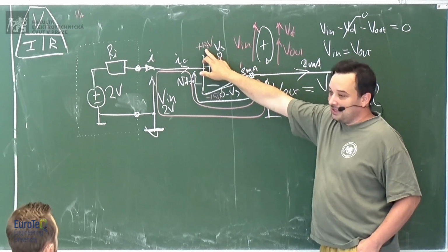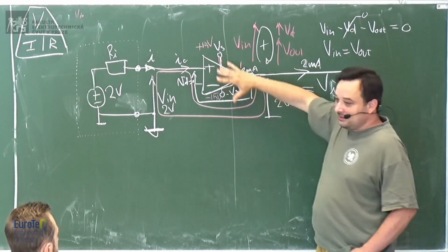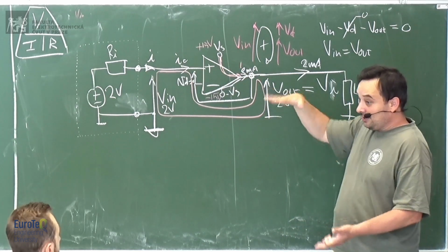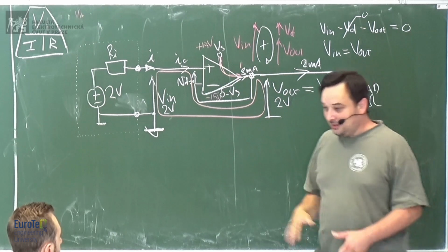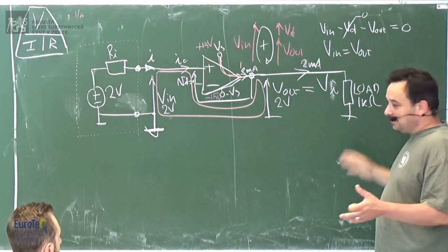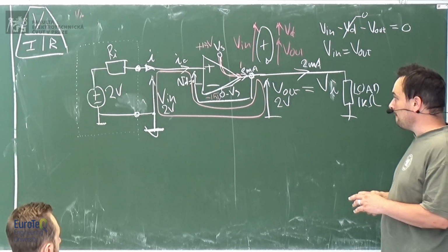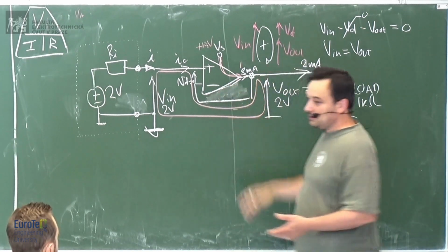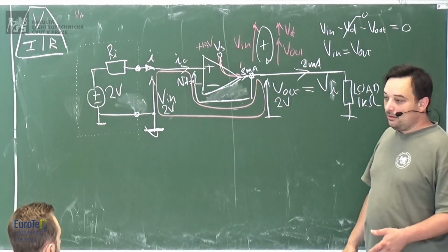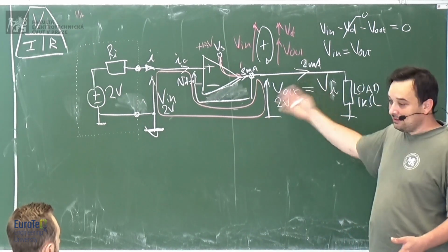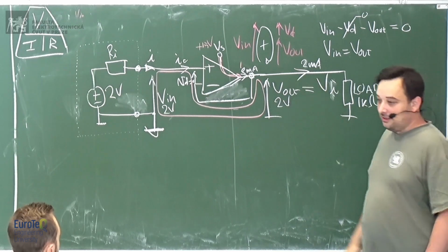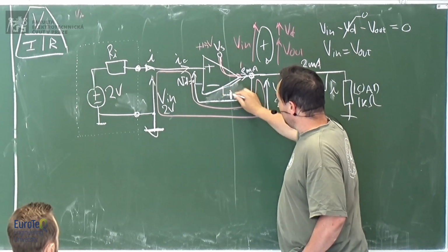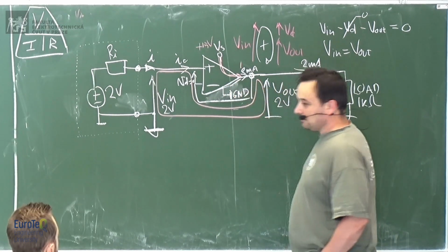Actually, you don't really arrive at 15 volts. Yeah, it's clipped just below 15. There are some amplifiers which arrive almost to the rail of the supply, but there's a voltage drop internally. There will be some minor voltage drop and so on. If you know that you are amplifying only positive, well, in this case there is no amplification, there is just a follower. So you know that you can connect this to ground, okay?